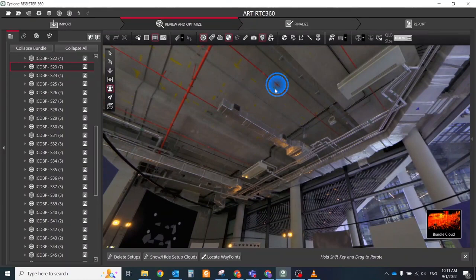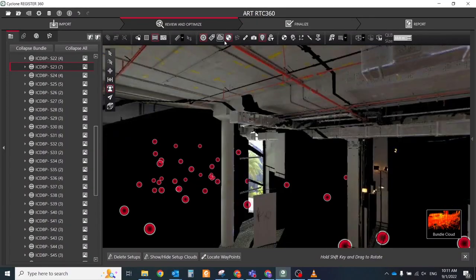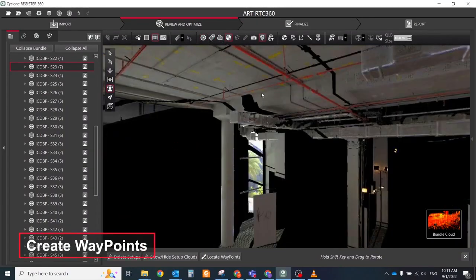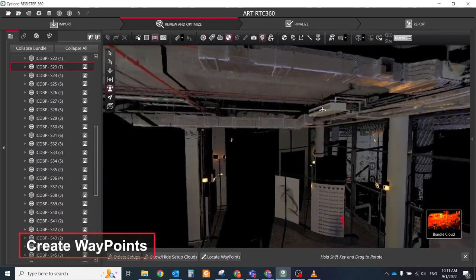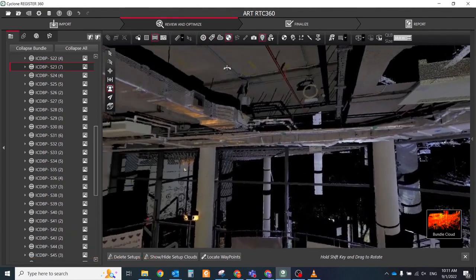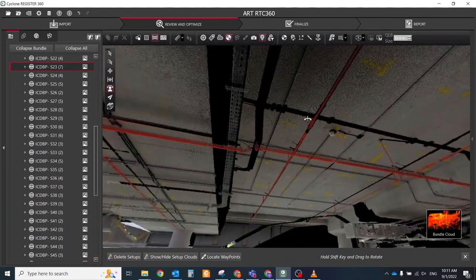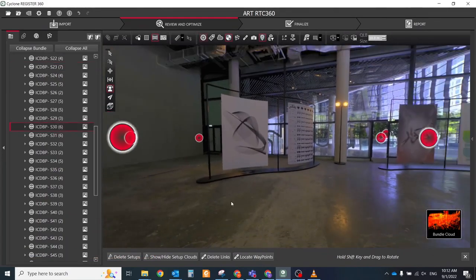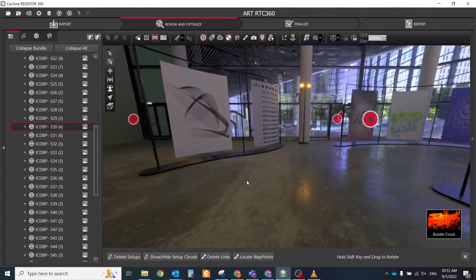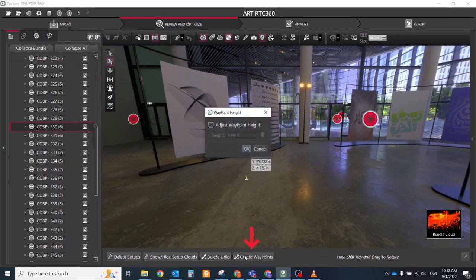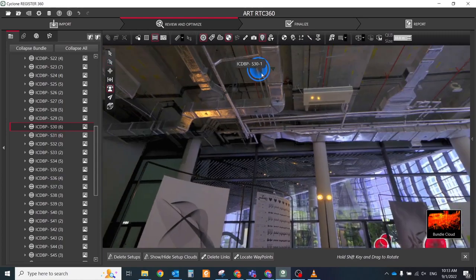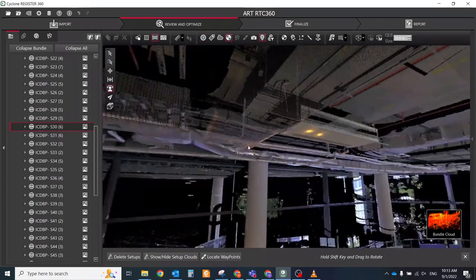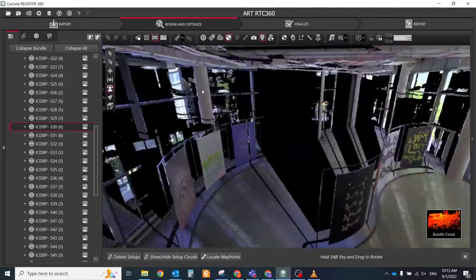Add additional waypoints from the setup view. It could be a helpful additional point of view, for example from bird view above all sight, from potential person or camera location, etc. Select points with the pick point tool and click Create Waypoints button at the bottom toolbar. In the pop-up window, input height from the selected point and click the OK button. When creation is done, you will see the new waypoint. Double click on it and the camera location will be transferred to that place.